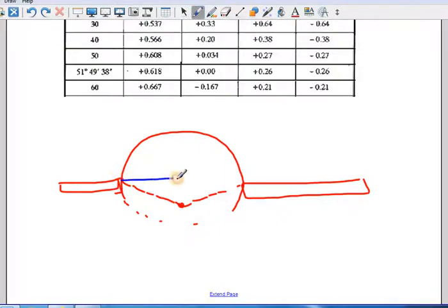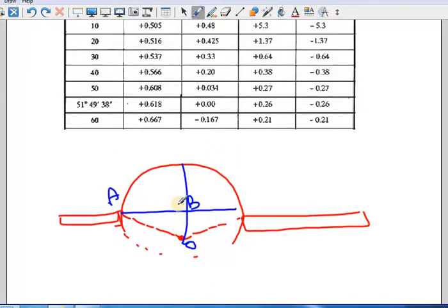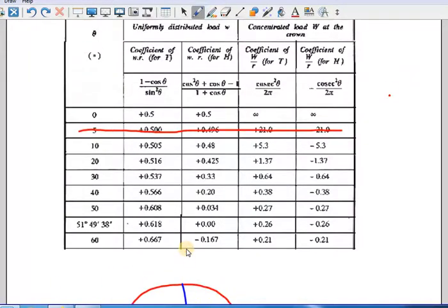This is the center point, this is A, and let us say this is B. AB is not your radius. The radius is AO. This is the radius of the part of the dome. We construct the dome only up to this much, but the actual radius will be this one, because this is not a complete sphere, it is a part of the sphere. So finding out the radius AO is important.